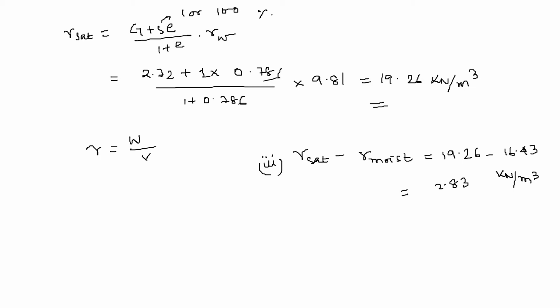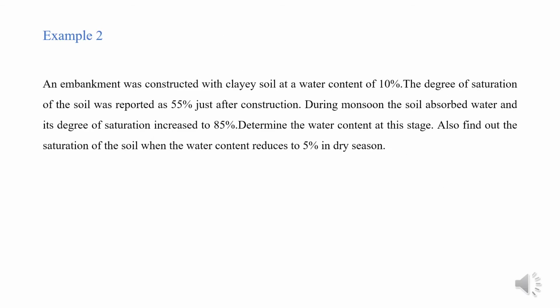So this is a very simple question with the various relationships between gamma, that's the unit weight, with specific gravity, saturation and void ratio. We also substituted when we found the relationship between water content, saturation and void ratio. We also showed how we use the relationship between porosity and void ratio. So through these various relationships, we can find out one property with reference to the other property.